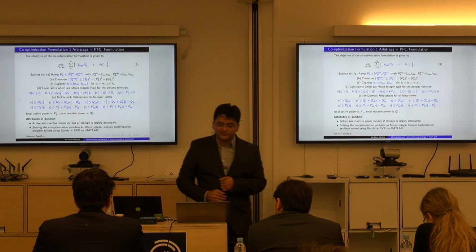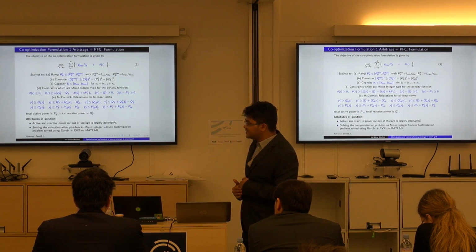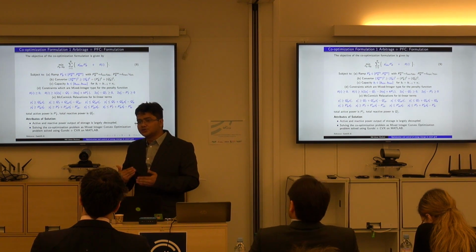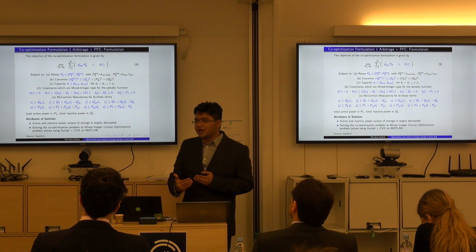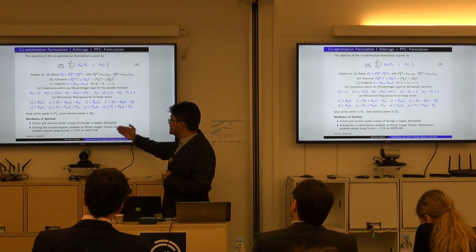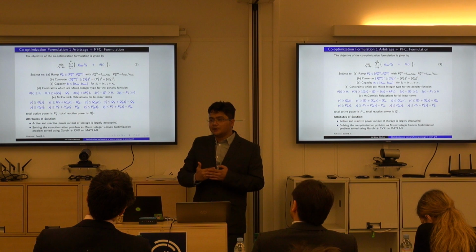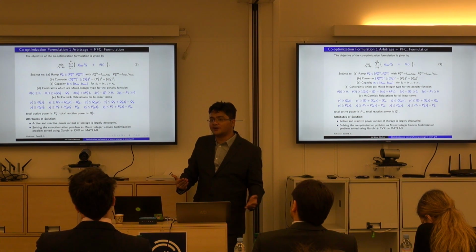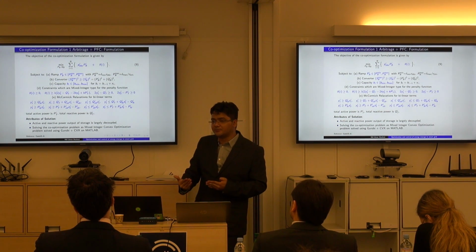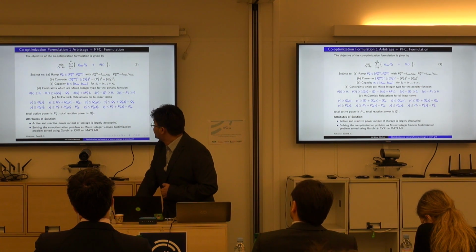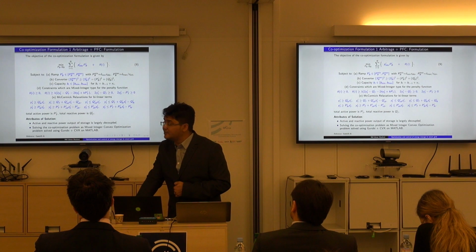So one key observation that I would like to highlight is that until and unless we make the converter size for the battery too small compared to the active power rating of the battery, we see that active and reactive control are typically decoupled. So providing power factor correction does not affect my ability to perform arbitrage. So we extend this formulation for peak demand saving.